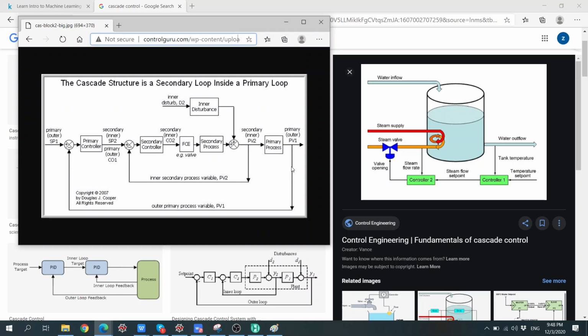If the temperature goes down, it sends the signal back, and it wants to see a temperature increase because it's going down. Then it gives the set point for the steam to come. So we need to have more steam, it says over here. So temperature drops, so we need more steam. It will then compare the steam set point to the current steam flow rate.